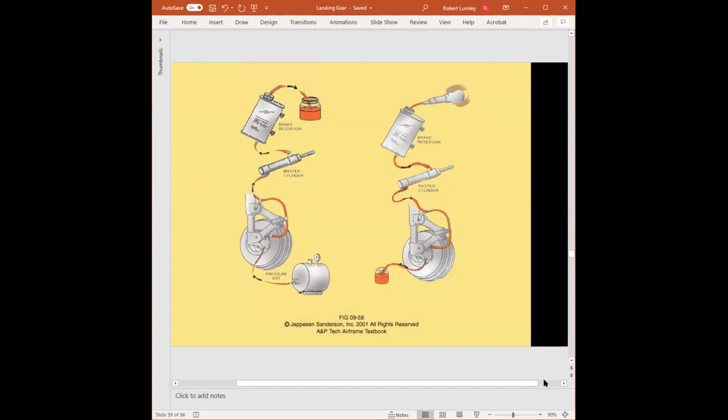We would look, sorry to say, it's not the easiest to be able to find, but it generally won't happen with rigid lines, but the flexible lines. So sometimes we might even have to disconnect and block off certain lines to see if we still have it, and then swap it out and stuff like that to verify. All right, but worn flexible lines are the cause. All right. By the way, that is bleeding of the brakes. We're almost done, folks. We're almost done.